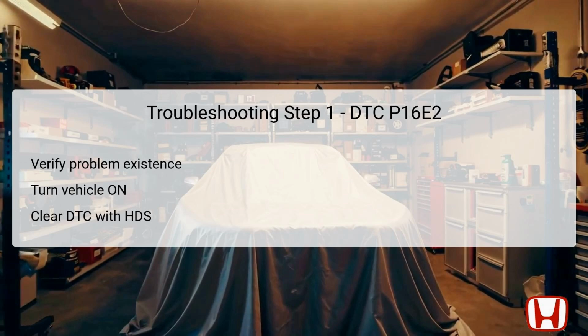This procedure ensures that the system has an opportunity to reset and recalibrate before rechecking for any pending or confirmed DTCs. If DTC P16E2 reappears during this check, it indicates the problem is persistent and requires further investigation.